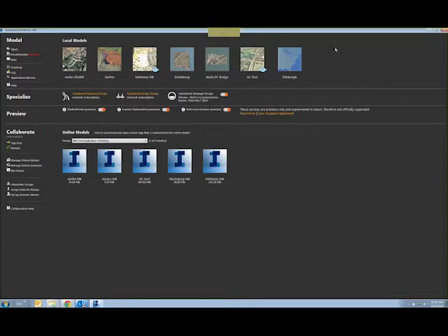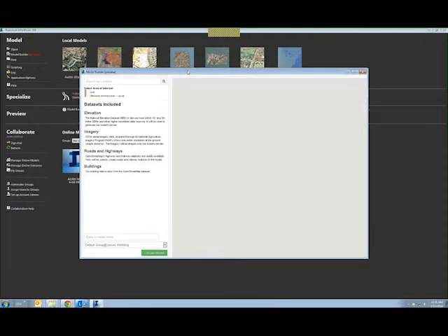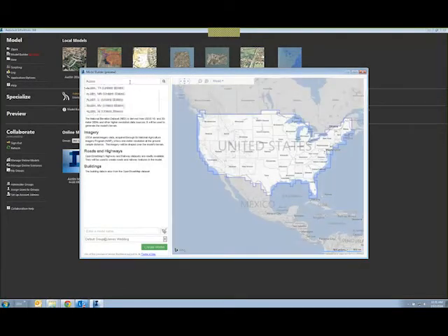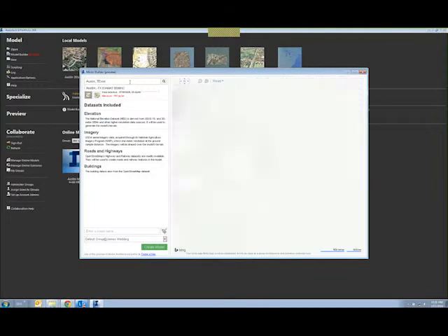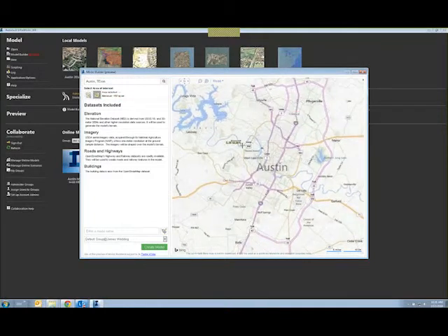And directly inside of InfraWorks, we've now built in a model builder. The model builder sits on the very front page and allows us to do essentially the same thing directly from within the application. Now, the model builder allows me to simply type in, again, a location. So let's go Austin, Texas again. It zooms in, and now I can begin selecting an area. In this case, again, that same downtown area, a little large. So we can pick approximately 150 square kilometers in this initial trial phase, but that gives you some sense of the amount of data we can grab in one pull.